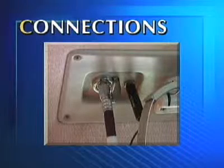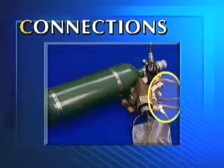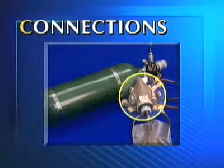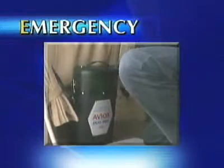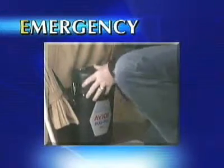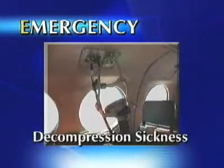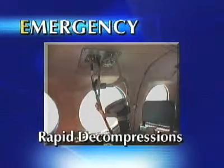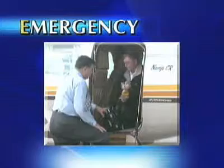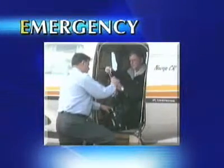Connections: ensure that all connections are secured. This includes oxygen lines, plug-in coupling, and the mask. Emergency: have oxygen equipment in the aircraft ready to use for those emergencies that call for oxygen: hypoxia, decompression sickness, smoke and fumes, and rapid decompressions. This step should include briefing passengers on oxygen location and proper use.